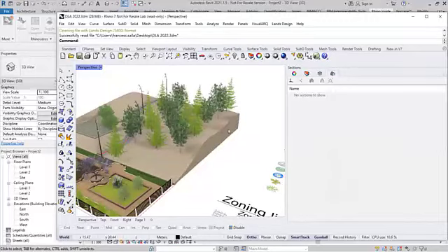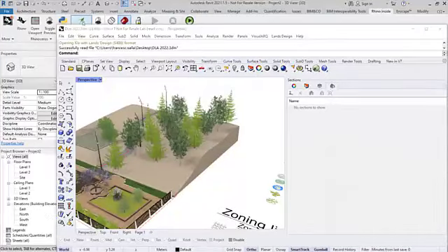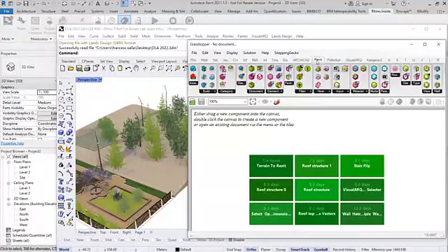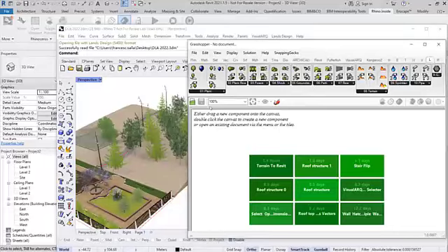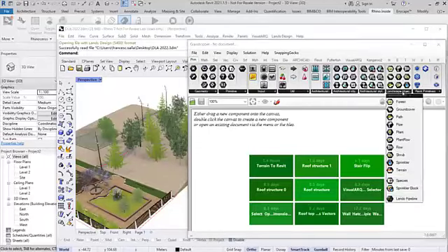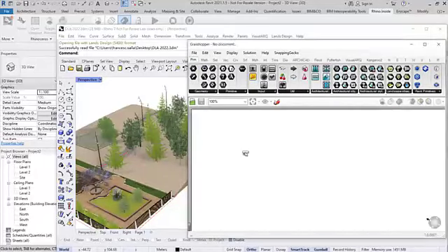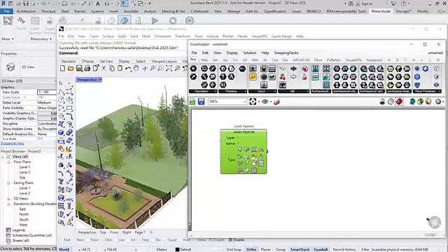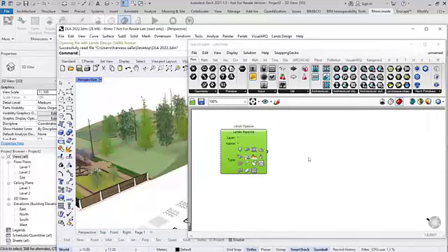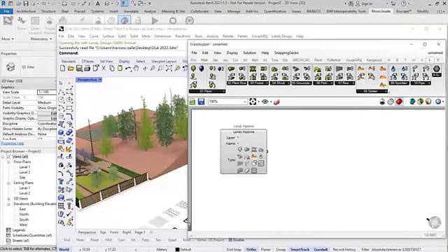So I'm going to show how to do this with the terrain as an example. So when we're in Revit and we launch also Grasshopper, we will find some Revit-aware components in Grasshopper. And for example, we can also use the Lands component to reference the terrain. I'm going to use this Lands pipeline. I'm going to double click on this terrain icon so the terrain is referenced. And since the terrain is basically a mesh, we can deconstruct that terrain.